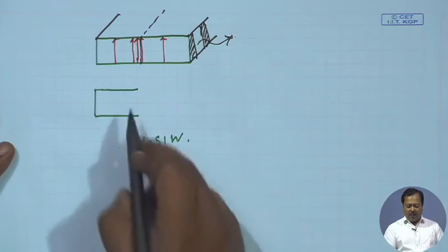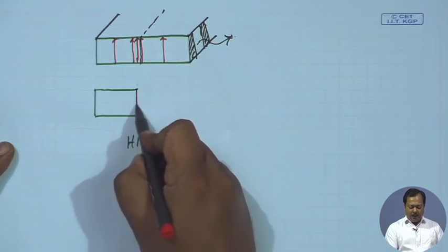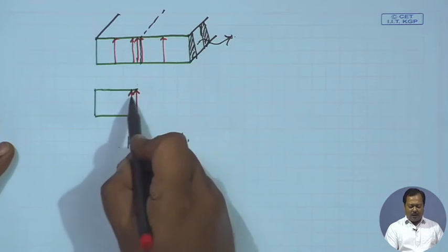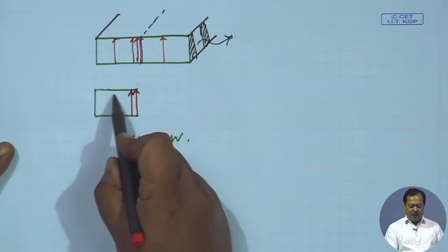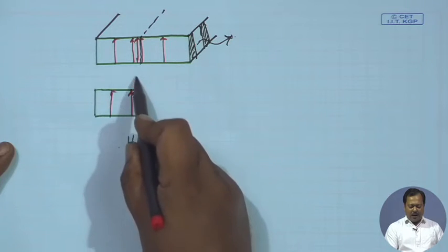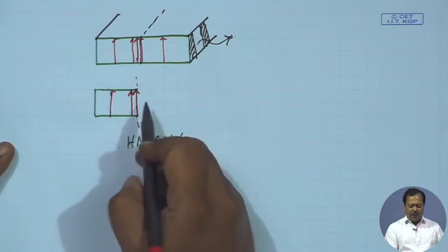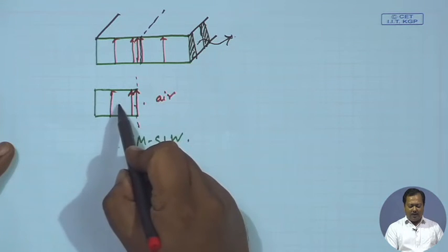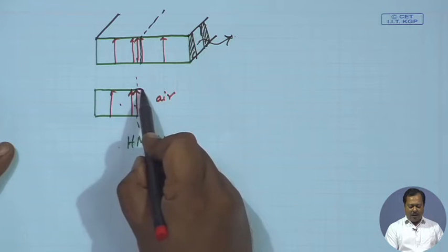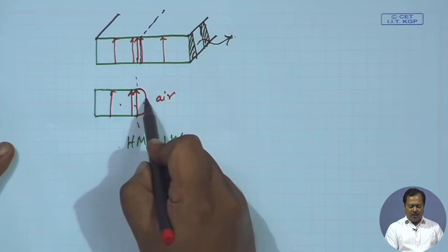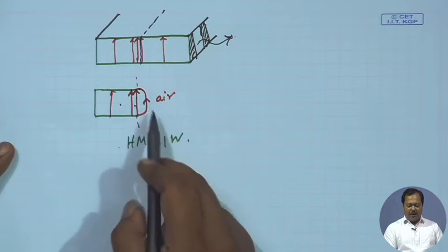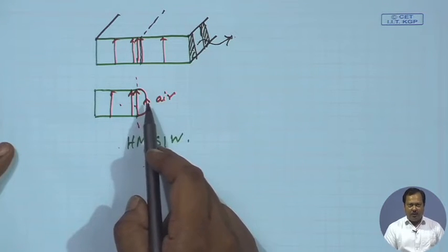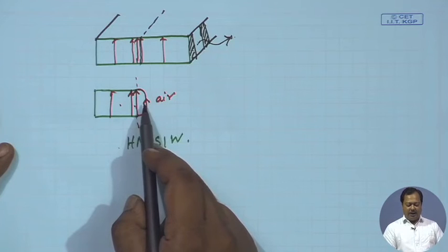But if I terminate my dielectric here on the central plane, we are expecting highest electric field, and then on the left hand side it will decrease. And if I terminate the structure on this plane, we have a dielectric-air boundary, this side air, left hand side let us say we have some epsilon r, and we are having some fringing field. But for this fringing field, electric field and magnetic field will be in phase quadrature. We do not have as such any radiation from this.